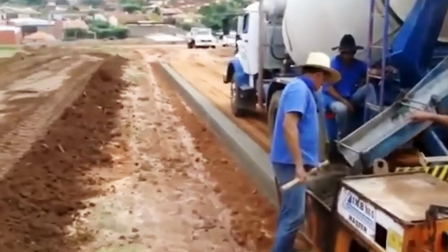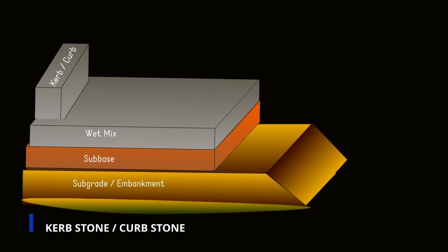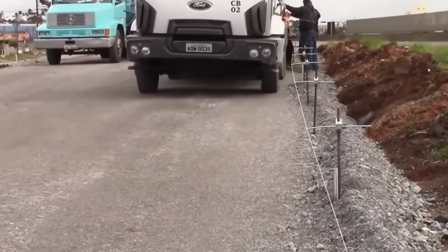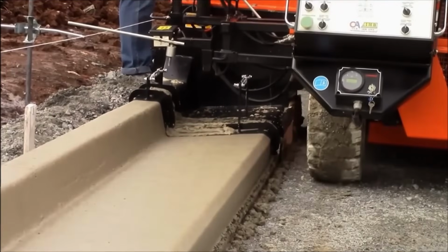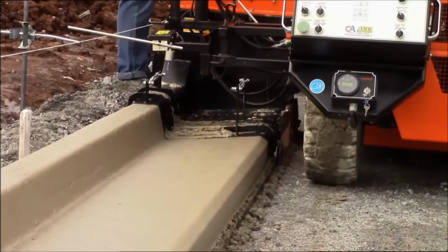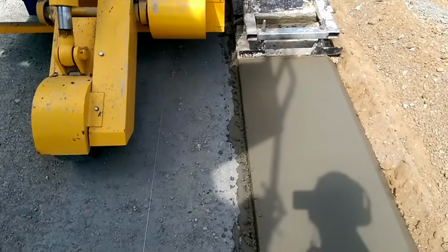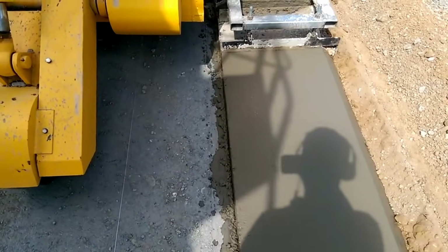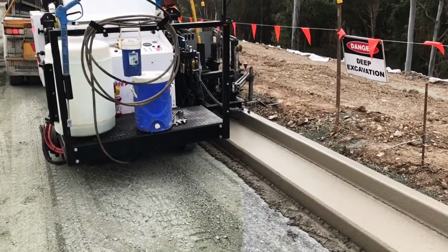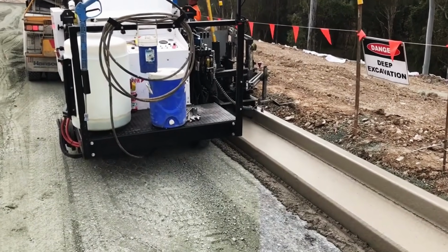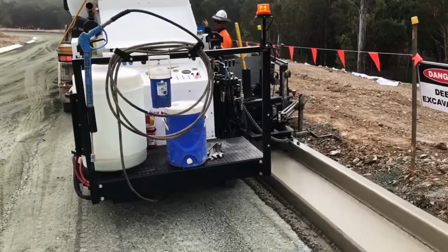The next item of work is Kerb stone. The Kerb stone provides clear physical and visual marking and delineation. It makes drivers aware of the pavement and greenery areas, helping in the proper demarcation of roads, streets, and car parks. It provides a clear view of the carriageway and helps in preventing any kind of lateral spreading from the carriageway. There are many types of curbs available.